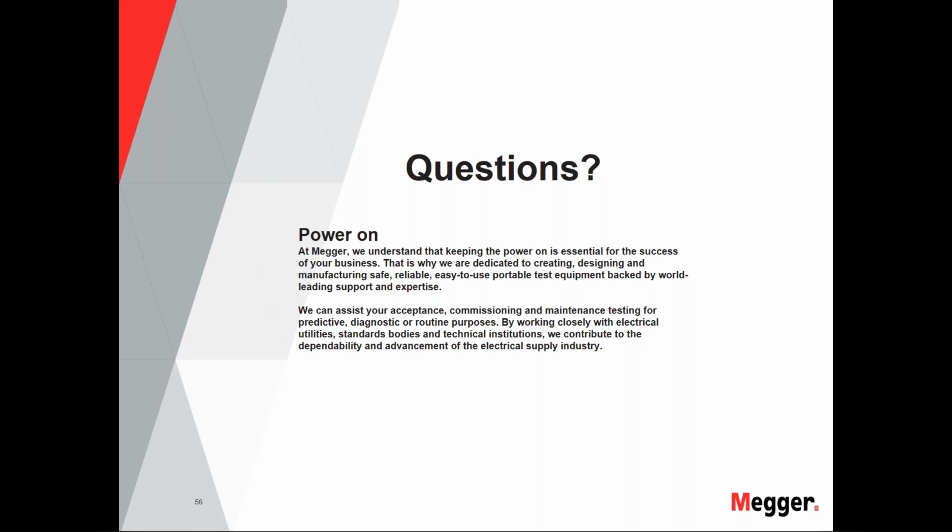Thanks. Next, we have a comment that I think you might want to follow up with. The comment is, I've seen reverse power used on a controlled shutdown to protect the unit from overspeed, to validate that the stop valves have actually closed and removed the power from the prime mover before opening the generator breaker. Yeah, I'd like to comment on this one.